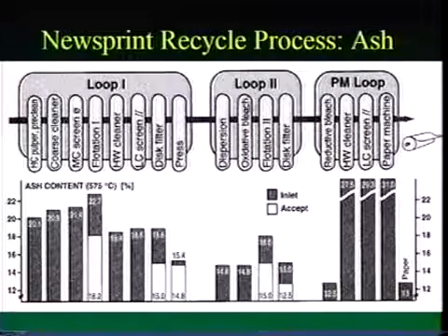We're actually using cleaner water in loop 2, so our ash levels are lower, except we go up in our ash content in flotation. And again, that's because we had to do a lot of dilution, and that dilution water has some ash in it. And the ash is actually good for flotation. Remember, we talked about that piggybacking, where the ash particles are actually used to agglomerate ink particles. And then a disc filter lowers our ash again.